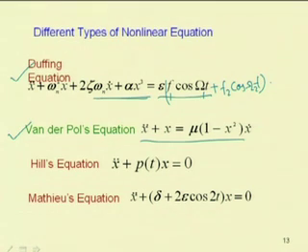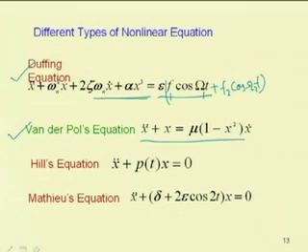For a linear system, one can easily find the solution, but a nonlinear system does not satisfy the superposition rule, so for each case you have to find the response of the system. In a linear system, when the equation is x double dot plus omega n square x plus 2 zeta omega n x dot equal to f1 cos omega 1 t, the response is x sin or x cos omega t. Resonance occurs when the excitation frequency omega 1 becomes equal or nearly equal to the natural frequency of the system.